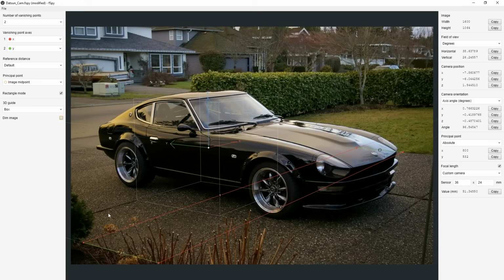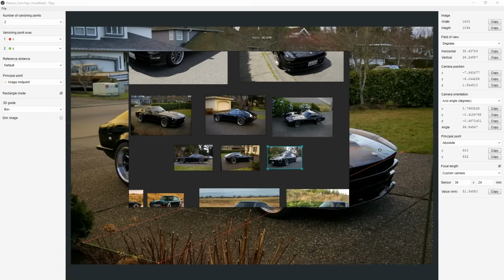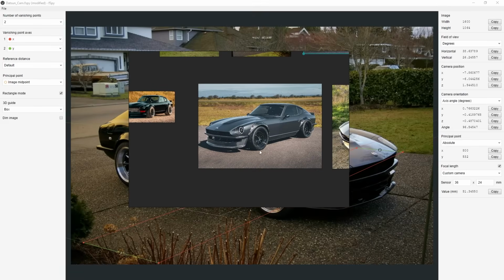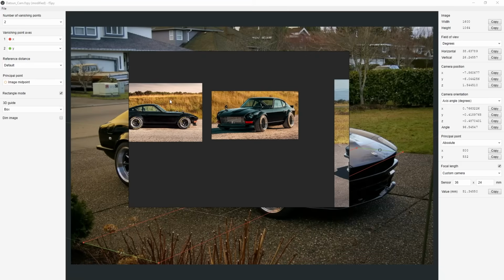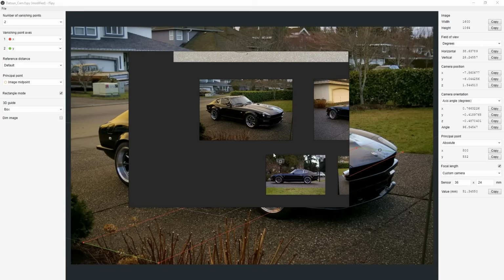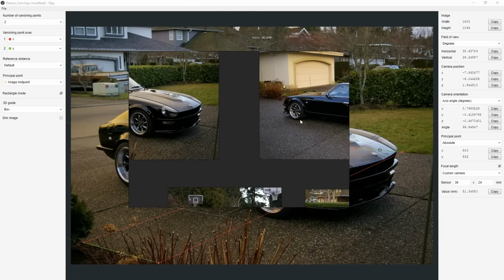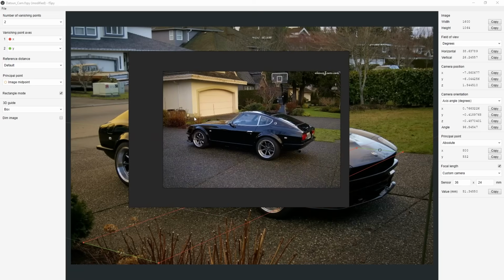And you definitely want to find images that you can use and have as guides. Obviously, if I take a look at my PureRef reference, some of these aren't really going to be helpful. Yeah, I have this horizon line, but that's not really going to help me camera match anything. So this one here worked really great. Maybe even this one from a rear view, you can put this in. Having these vertical lines going through your reference is perfect for camera matching. So you can bring those inside of Maya.